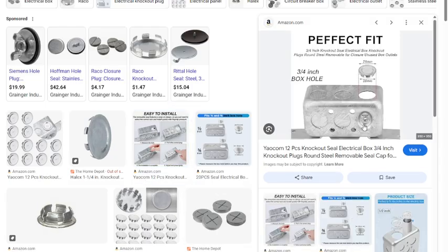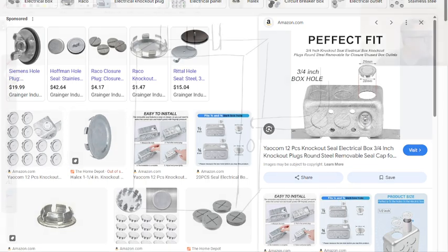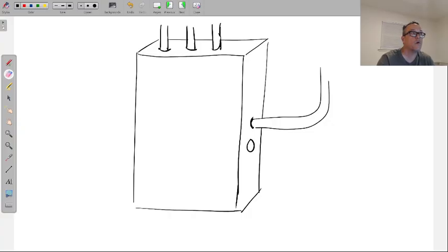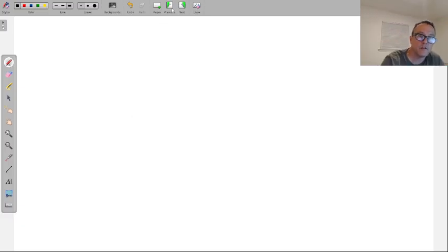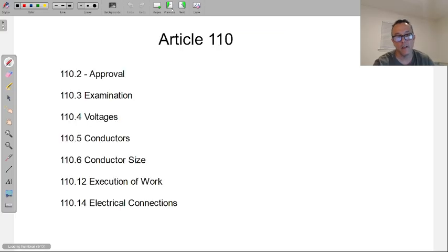All right. Now you can get away with this sometimes if there's a junction box and then there's drywall over it, and the inspector doesn't see it anymore. But this is why inspections happen all phases of the job, before the drywall has been put on the walls and before we start to seal things up or seal the walls up. The inspector does come out and take a look at everything. And make sure things like that have been taken care of, right? So knockouts, and also they're looking for things properly supported, etc.